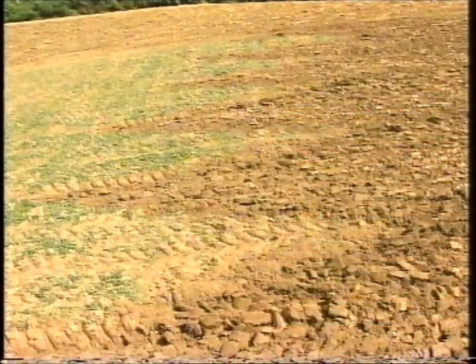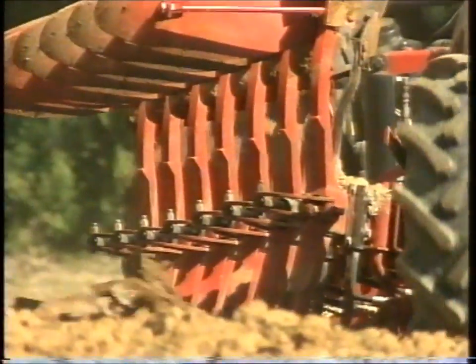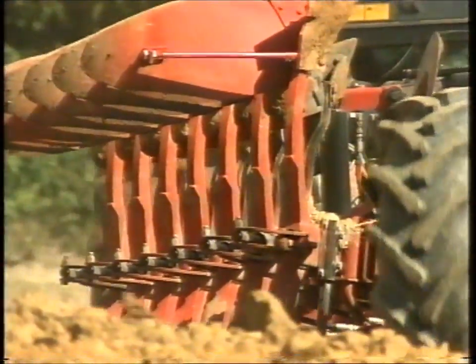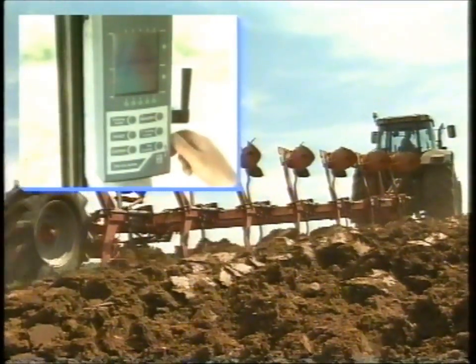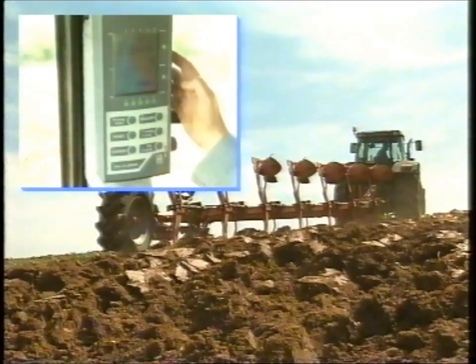Secondly, it's extremely difficult to maintain an even headland line without dual control. This is because, since the rear of the plough reaches the headland later than the front end, the driver requires a high degree of concentration to maintain a reasonable finish. This is even further complicated where the field has an angled headland to the line of work.